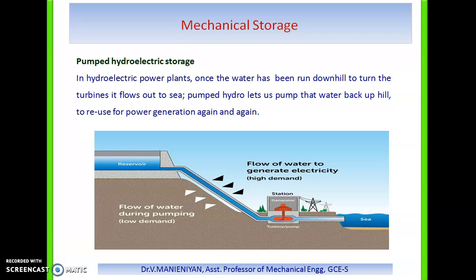This method of solar energy storage has the advantage of avoiding the intermediate conversion of solar energy and producing AC power directly. In this scheme, water acts only as the working fluid. Once the initial volume of water is secured, the only flow needed would be makeup for loss of water by evaporation. Therefore, the scheme does not need to be near large bodies of water.